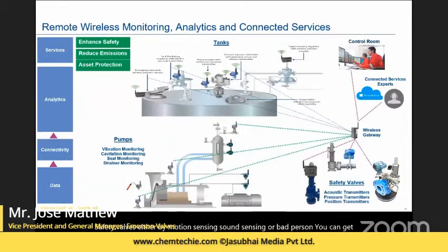And then the valve vendor's experts can also look at analytics based on that and give feedback as well as maintenance actions to be taken. The same applies for pumps as well. You could monitor a pump remotely. It could be vibration monitoring on the pump, cavitation monitoring, seal monitoring, or whether the strainer is getting clogged. All those can be monitored wirelessly, and again looking at the data and the analytics, you can then take advance action.